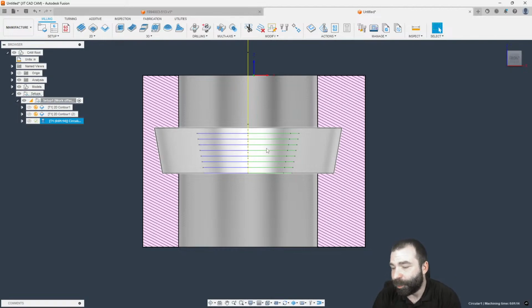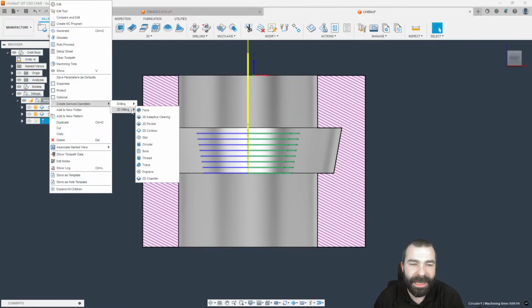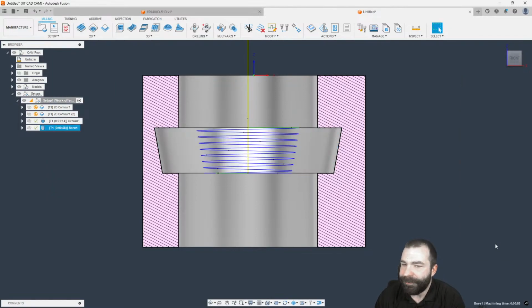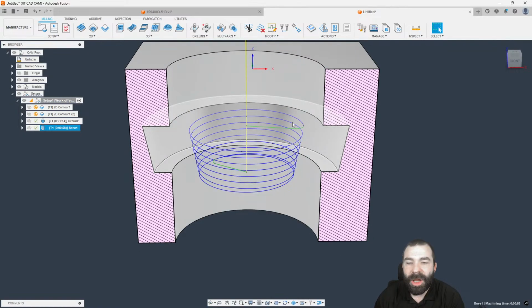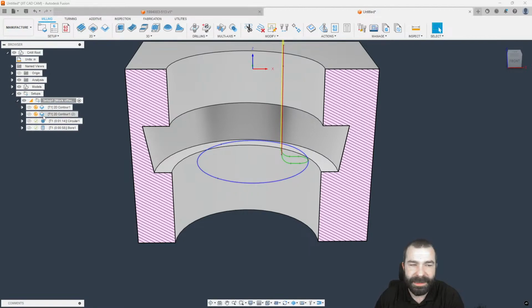So you could, 100%, Michael, you could, instead of using circle, if I actually went in and did a bore toolpath instead, again, you're going to have to play with your Z heights, of course, but notice how I'm helical boring down inside that part, right? Now, keep in mind, your first initial pass of that bore is always at a taper, right? So you would still need to do an upper kind of 2D contour to clean up that top edge.